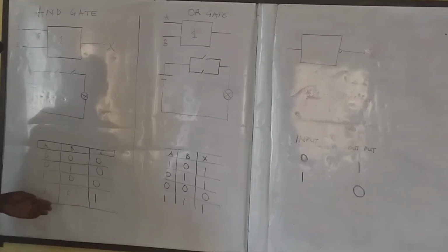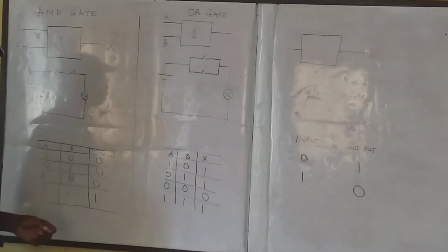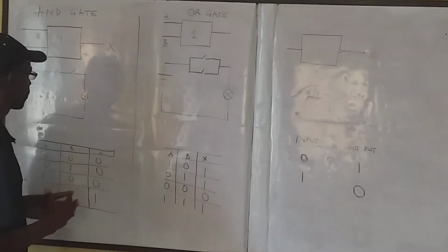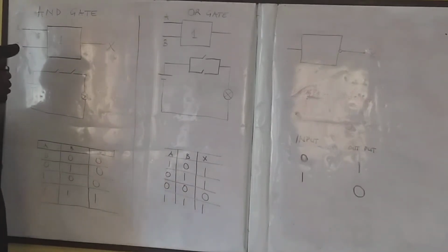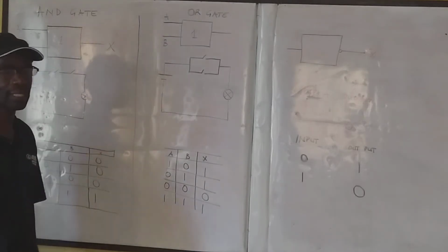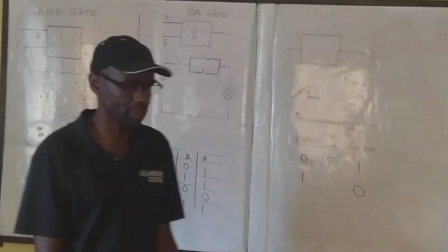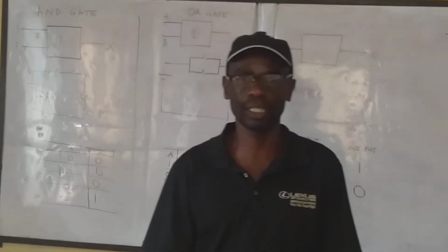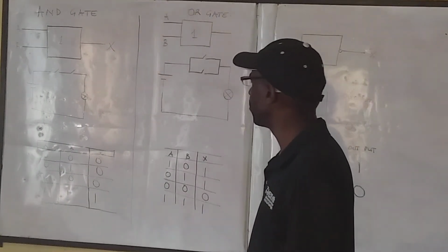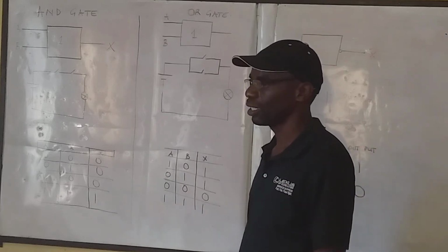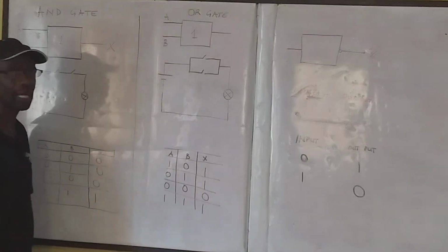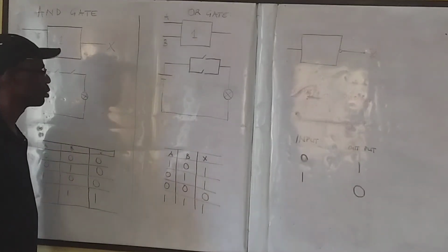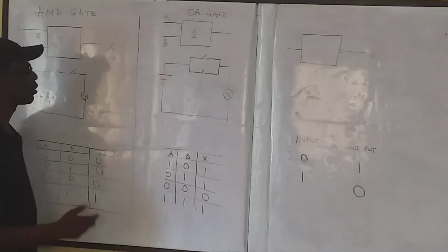The gate elements receive inputs that they will process to produce outputs. Typical inputs on the motor vehicle come from sensors. Then typical outputs on a motor vehicle system go to actuators, and the typical actuators that we have on the motor vehicle in the engine management system, for instance, are the coil packs and injectors. Most probably the idle control actuators, the typical actuator which receives output from the computer.